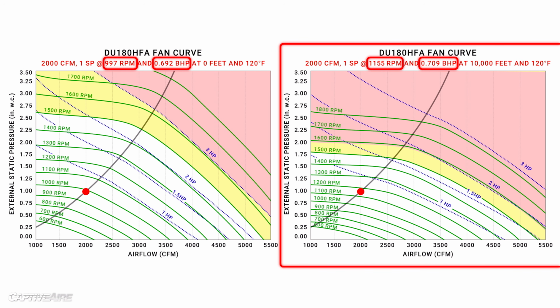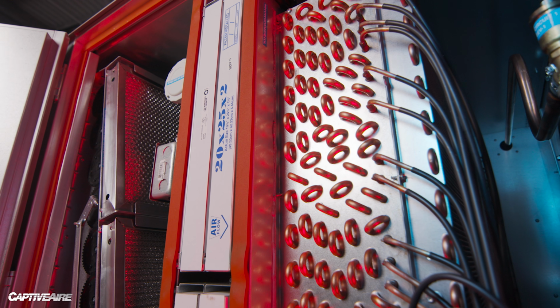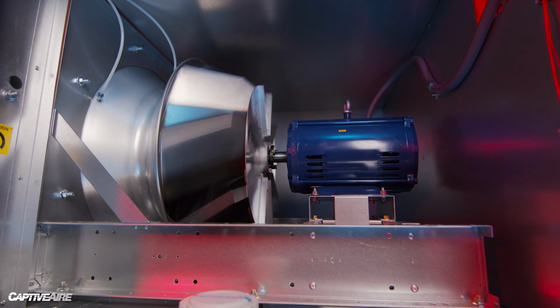And this is why details matter. When looking at these calculations, we have to understand whether those static pressure specs were given at sea level or at the right elevation, because that changes everything. The same goes for temperature. Do we have the correct temperature that the fan is going to see? It matters. And things can get even more complicated when we're talking about heating and cooling.